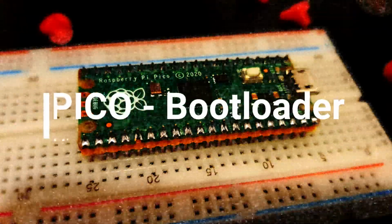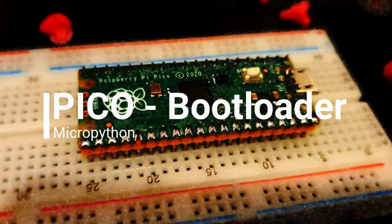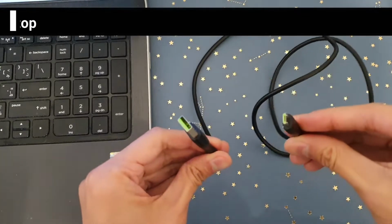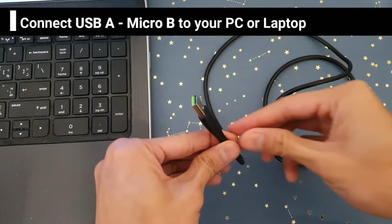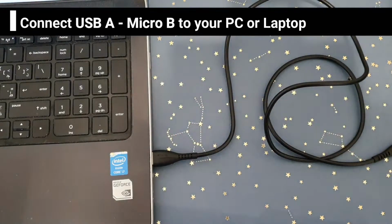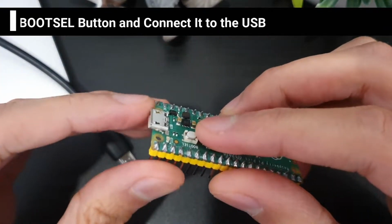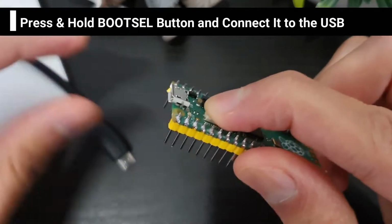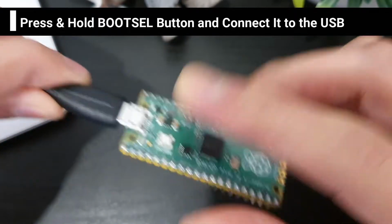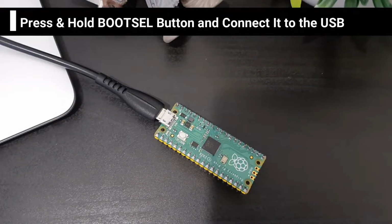Okay, so the next step is to set the Pico board as a bootloader to install MicroPython in it. To do that, we need a USB-A to micro-B type of cable, and then we connect the USB-A to our laptop or PC. Now we need to connect the micro USB-B cable onto the Pico board while pressing the BOOTSEL button. This will set the Pico board into bootloader mode, such that we can install MicroPython in it.